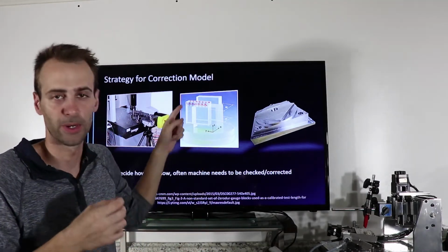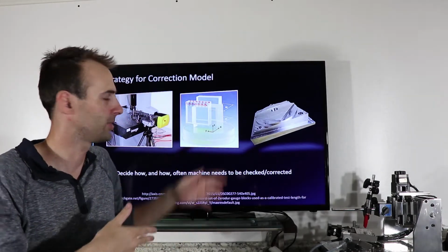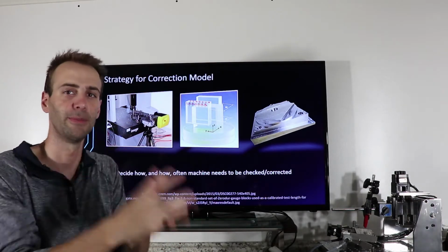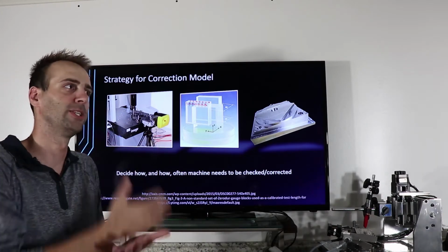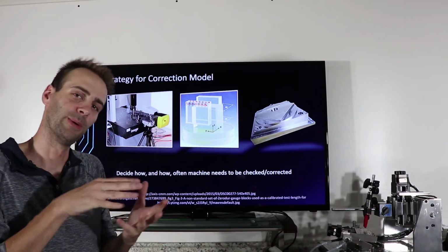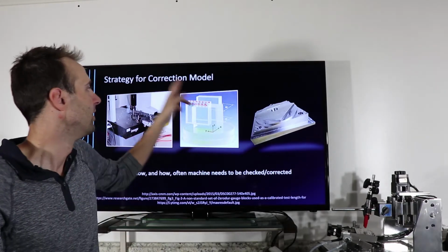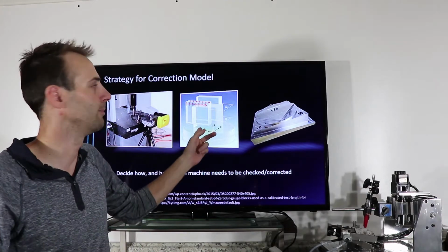If you were to put your dial gauge in the machine and tram along one of these flat faces and you don't see any movement on the dial, it means there's no errors, right? So you don't need a direct measurement technique to decouple every single error. You just have to be smart about where you put your dial indicator and what you put in that machine and where.